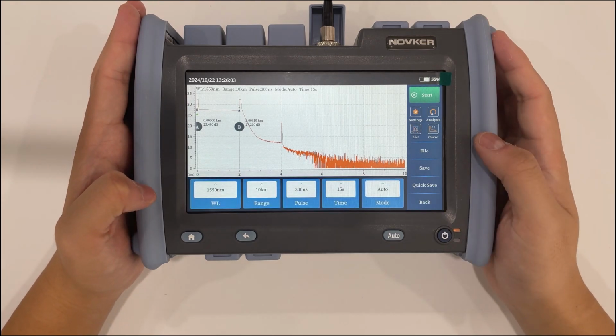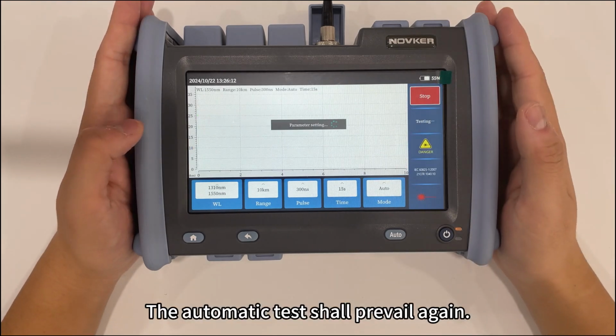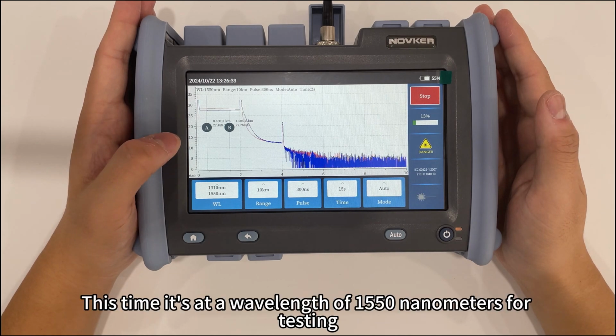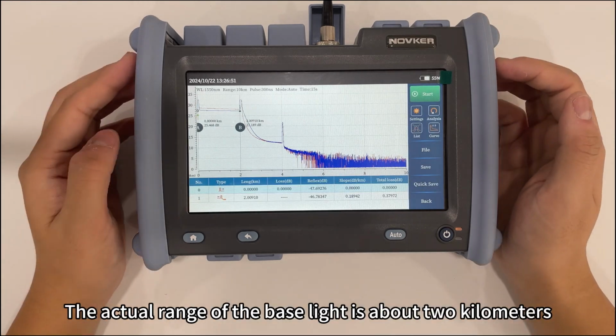Optical fiber. Now select dual wavelengths for simultaneous testing, again with automatic test. At this point, the device will first test with a wavelength of 1310 nanometers. After the test is completed, it tests at a wavelength of 1550 nanometers. You can see the actual range of the fiber is about 2 kilometers.